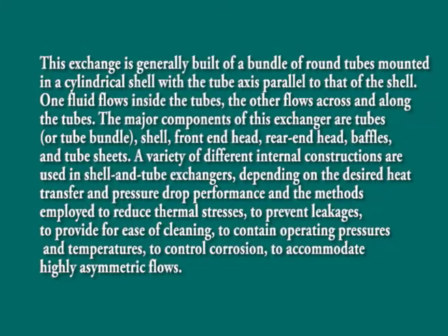The major components of this exchanger are the tubes or tube bundle, shell, front end head, rear end head, baffles, and the tube sheets. A variety of different internal constructions are used in shell and tube exchangers depending on the desired heat transfer and pressure drop performance and the method employed to reduce thermal stresses to prevent leakage,